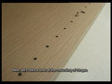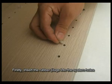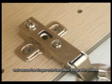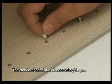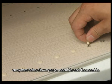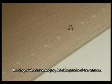Next, let's have a look at the mounting of hinges on the system holes. Firstly, insert the rubber plugs into the system holes and secure the hinges onto the plastic plugs with screws. In the end, put the plastic caps on the system holes. The standard technique of assembling hinges on system holes allows you to assemble and disassemble the hinges without damaging the side panels of the cabinet.